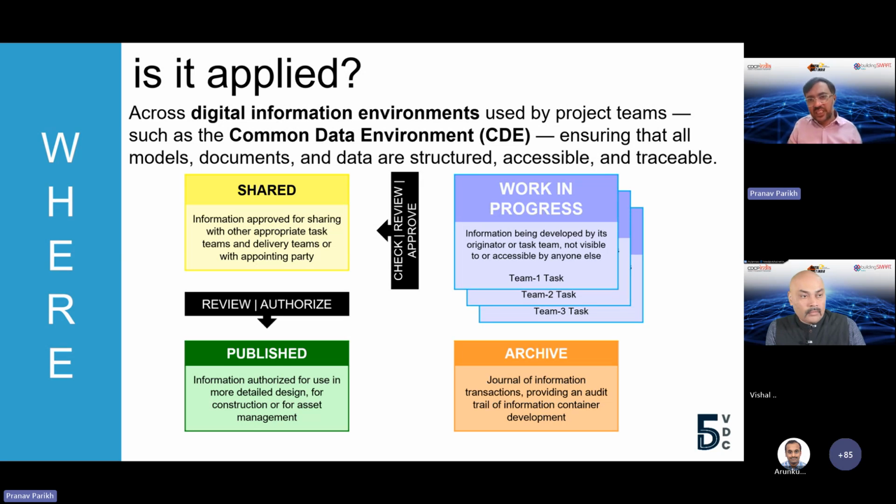So from an ISO 19650 point of view, any document or file in a CDE environment has a work in progress status, which means I have uploaded this file in a CDE, but I'm still working on it. It is my private space, right? This is where I'm actually developing that particular drawing, that particular document, whatever we are doing. Now, you can do this outside the CDE and then upload, but it always goes into the CDE as a WIP first, right? Wherein you upload that particular file.